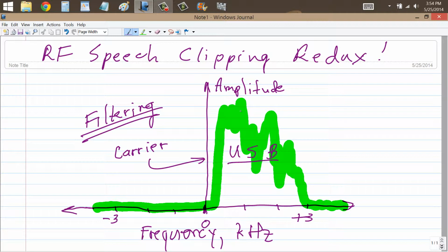So what do you do here? Normally, in order to get one sideband or the other, you need to employ a selective filter with what they call a rectangular response. And I've made a video about that, and I believe it's in this same playlist, Teach Yourself Electricity and Electronics Miscellany. Rectangular response just means that it passes energy within a very well-defined range of frequencies.